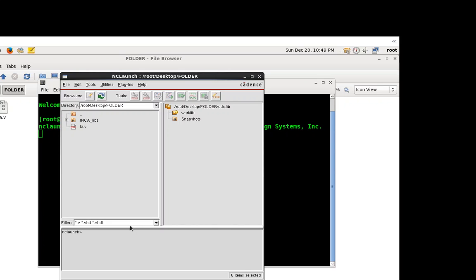So now the file is there, and this is just a library file related to some basic primitives required for Verilog, because we have chosen Verilog design. So now we are ready to do the simulation. Before we go, the simulation itself is divided into 3 steps. In the first step, it will check the syntax of our Verilog design. That is, are you giving legal statements?